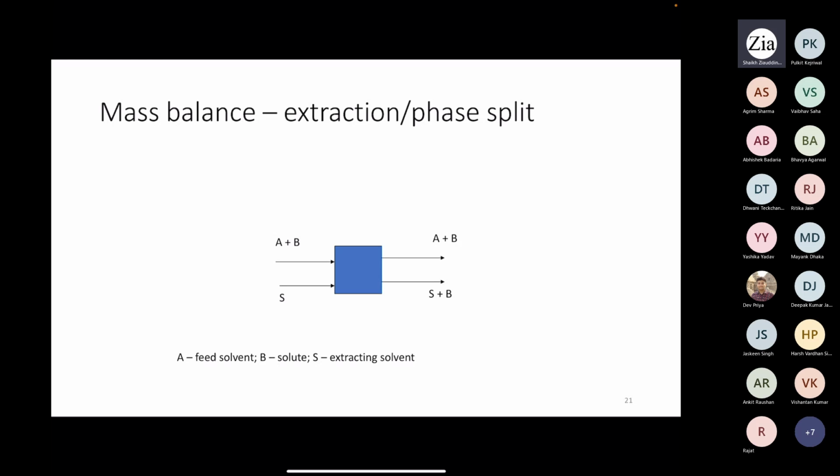So here, the distribution coefficient of that particular material in different solvents is also very much important. When you try to design this extraction unit, you also make sure that the distribution coefficient, or partition coefficient, is considered, and also the kind of solvent you require to improve the extraction efficiency. And also you need to make sure that the kind of material you use should not have any adverse effect on the product quality.